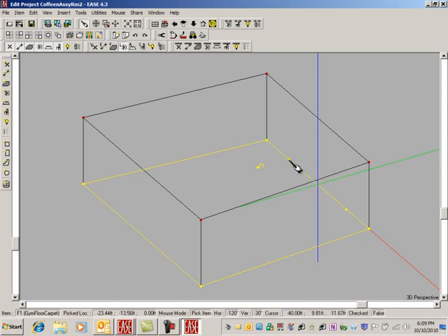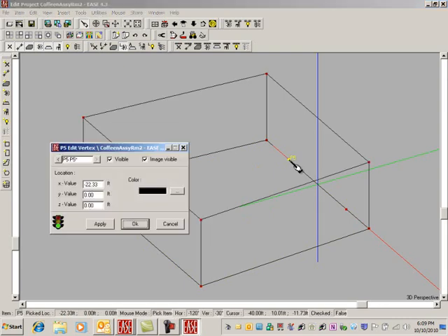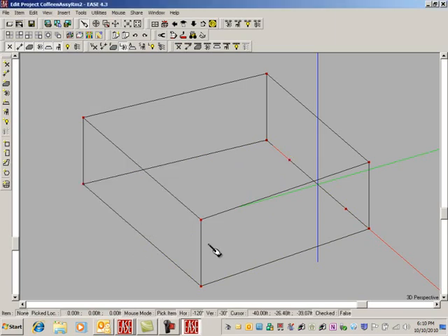And we could add that stage floor now, and we know that it's in 4 degrees. Well, what if we went to this guy and said, let's duplicate this guy. The stage is 25.5 feet deep. And if I say right mouse click, duplicate, I could use these polar coordinates.